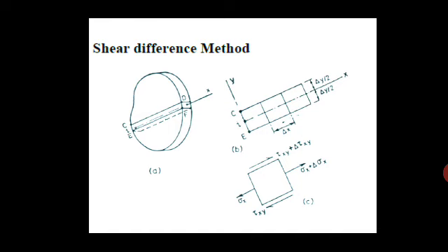Here, the step-by-step integration is carried out along a selected line, starting from a point where one of the normal stresses is known. Generally, the initial point lies on the boundary, where the individual values of sigma 1 and sigma 2 are known.